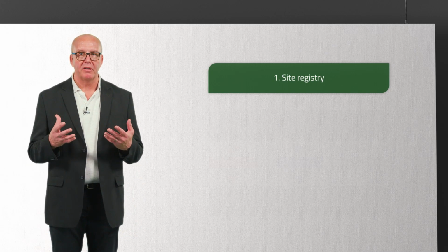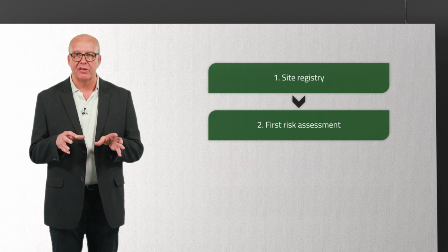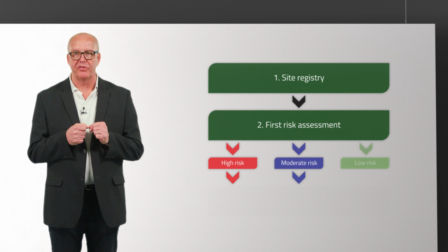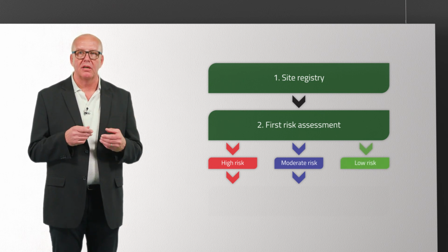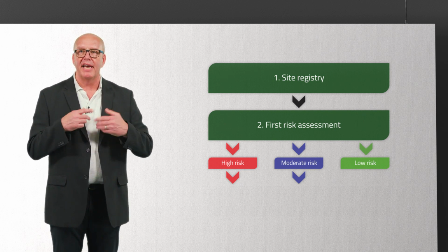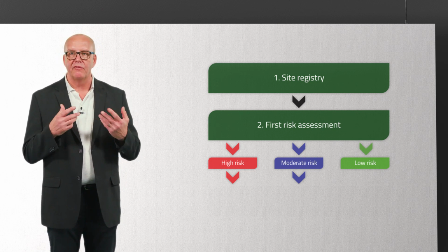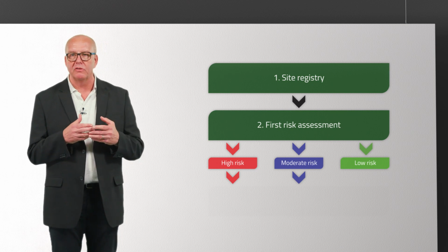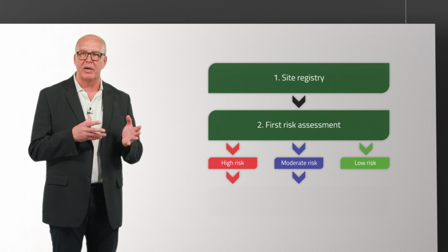The second step is risk evaluation. A first assessment of risks is designed to distinguish between high, moderate and low risks. Potential risks are hydrogeological, landfill gas, stability, odors and health risks, as well as ecological risks. Different tools are available for risk assessment. With an expert's help and experience, crucial parameters are assessed and sites are categorized.